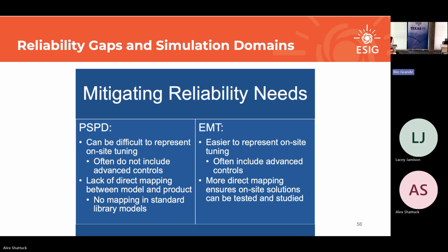So in situations where, for an active power set point change, I'm getting an argument with ERCOT and they say you're not moving fast enough, like I asked you to, maybe the manufacturer product has 3 ramp rates and you need to tune some combination of those 3. The PSPD might only have 1. So how do you make a solution that works with both? It can be very difficult. And again, putting it actually into the field is the last, most difficult piece as well.